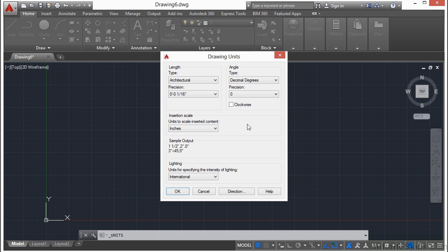Not only do you have to work in measurements of length, but you're going to need to work in angle measurements as well. AutoCAD has a lot of choices for that too. You can display your angles in decimal degrees, and that's all controlled here. Degrees, minutes, seconds: surveyors will often do this. You can display it in gradians, radians, or even survey units. So survey units or degrees, minutes, seconds can be used for surveyors, but you might see them in either format. So if something doesn't look exactly right, take a look at it.